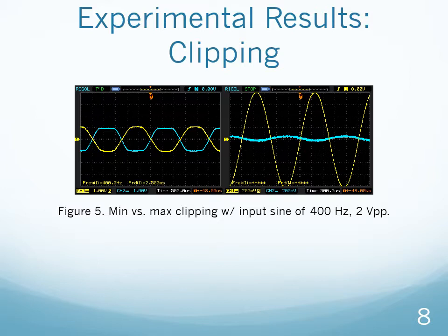And sure, you'd have to boost the volume a little bit, but what actually ended up happening is that the left-hand one, when you had the clipping at its maximum value but still kind of lopping off the very top, actually resulted in the most distortion, whereas any of the lower voltages clipping more resulted in essentially just a volume decrease and a little bit of distortion if you cranked the master volume back up. That was not exactly what I expected to see, but I still got the effective distortion and the ability to turn it off by actually clipping more, so it's kind of just the opposite.